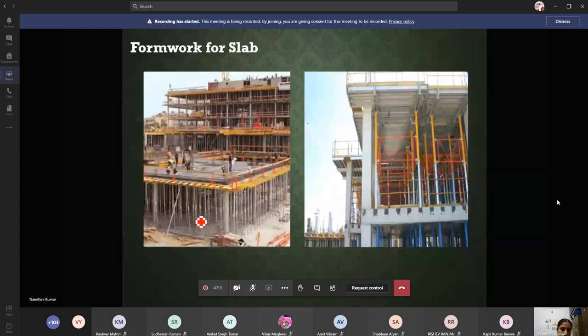These are the vertical members that are laid. You have the sides, that is the beams, and the inner part you have the slabs. The person standing on the reinforcements is checking for verticality and they are going to pour the concrete into the slab. Here you can see this floor is done. You can see it is leveled, which means it is uniform. Now we are moving to the next floor or the roof. Here they are going to pour the concrete, and for that they are providing additional supports.